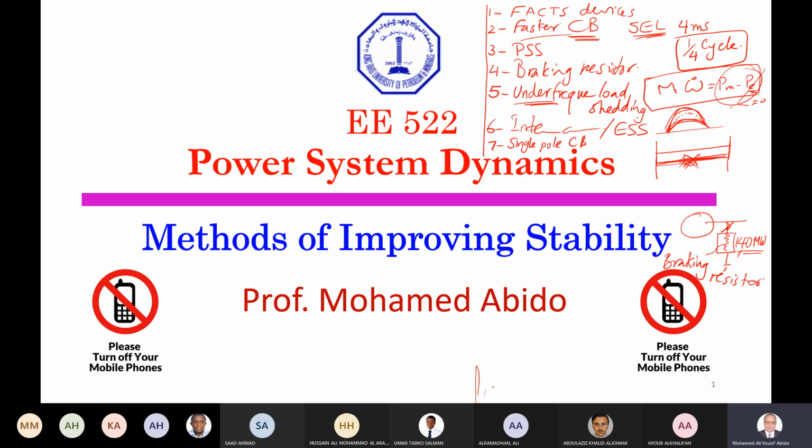So if you remove the faulted phase for 1, 2 or 3 cycles, and then you close the circuit breaker back after 3 cycles, 50 milliseconds, and fortunately the fault is cleared by itself, you are back to normal three-phase system operation. So would this help the system stability, Abdulaziz, or not?